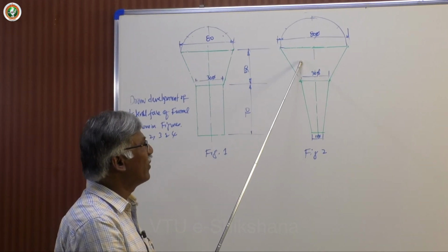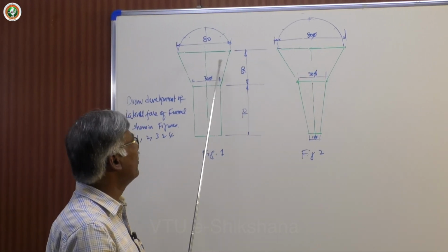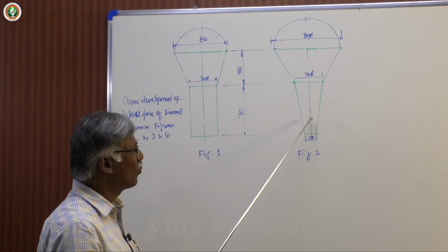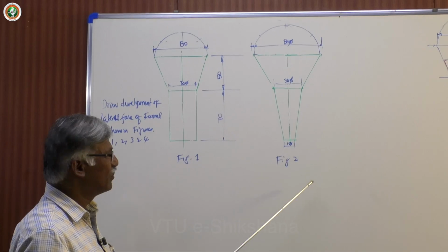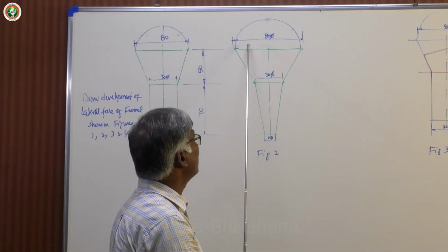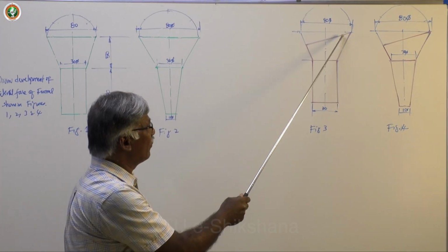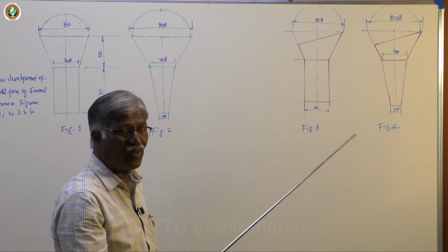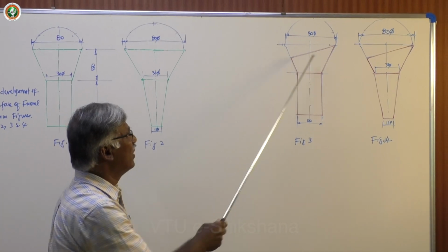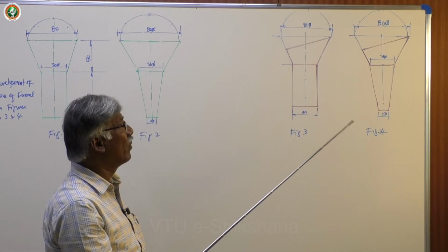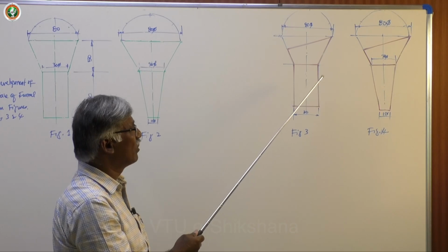Here it is again part of cone, that is frustum of cone. This is also frustum of cone with 30 and 80, same thing. And here I have again frustum of cone with 30 base end and the 15 top end or the small end. So here I have the same type of frustum of cone, but it is truncated with the big end reference. So with the right top corner we have a section plane. Assume that the section plane is cutting the frustum of cone passing through this right extreme point, and then at an angle of 15 degrees, or any suitable angle given.